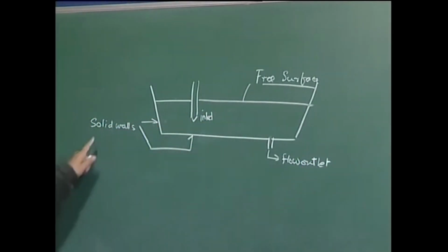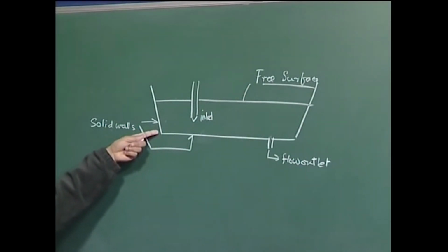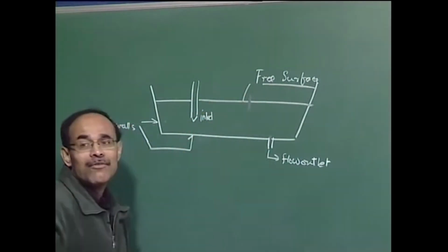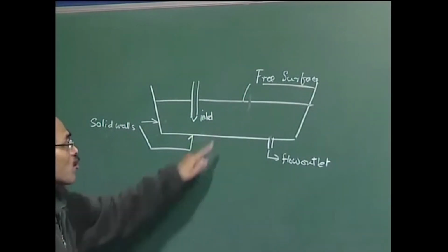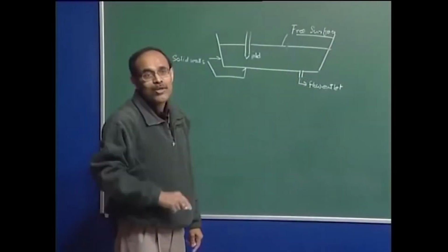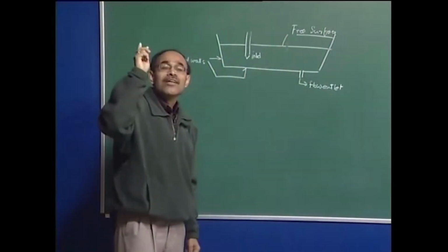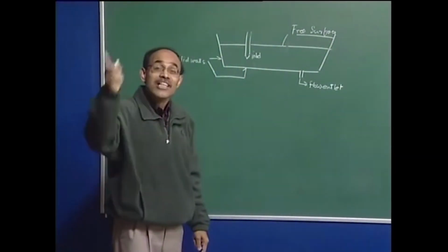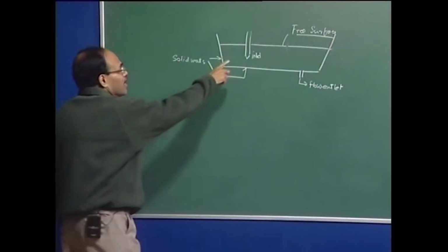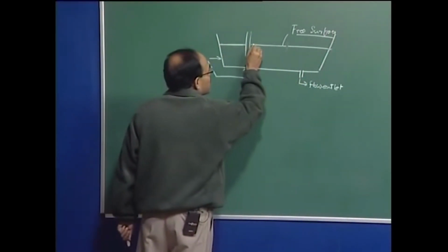of, for example, at solid walls we know that there can be no velocity. So, the velocities are going to be 0, no slip condition. At the free surface, if it is stagnant, we know that the vertical component of the velocity is going to be 0 because it is stationary, it is neither moving this way nor moving that way. Note that we have 3 components of velocity. So, on each of these surfaces, I have to write or provide boundary conditions on each of the 3 velocity components. This is very important for us to remember, but nevertheless inlet flows are known, outlet flows are also known in this particular case because I am considering a steady state scenario.